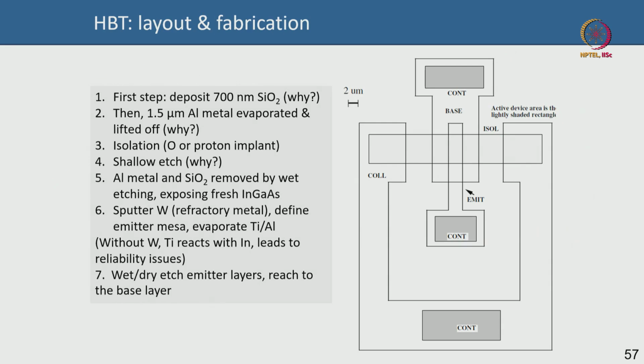All right, so then we come to, quickly again, a little bit of a standard fabrication approach for a compound semiconductor HBT. More recent and advanced compound semiconductor HBT fabrication processes are fairly complicated and much more elaborate with a lot of masks, but the basic premise remains the same. So we'll only go through the basics. Okay, we're not going to discuss the more advanced ones, because the fabrication of compound semiconductor HBT itself can be a course. It's very vast, just like silicon germanium or silicon BJT fabrication can be very vast.